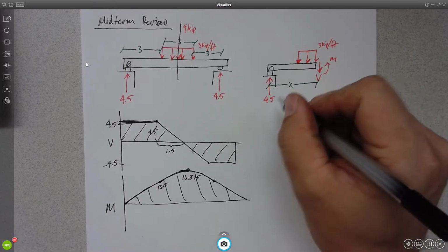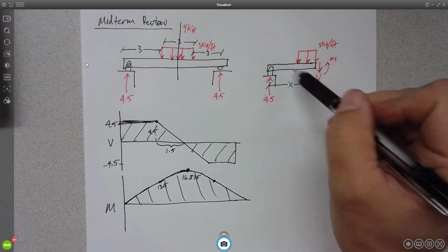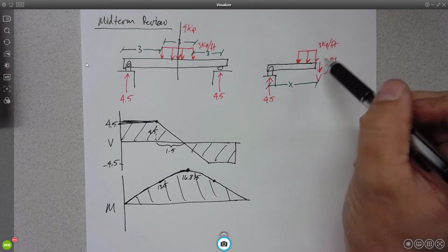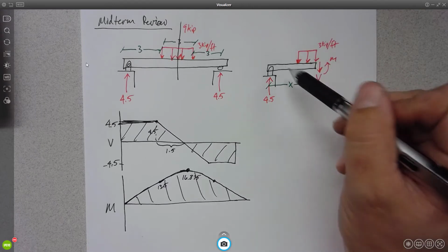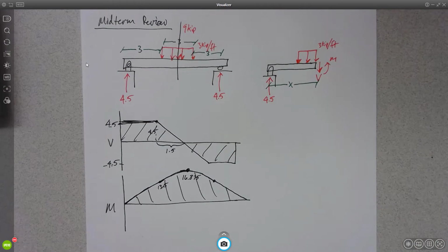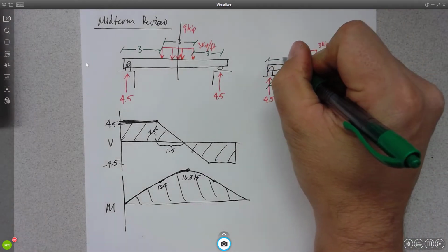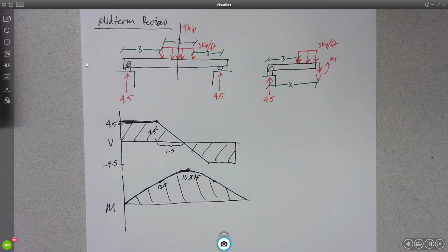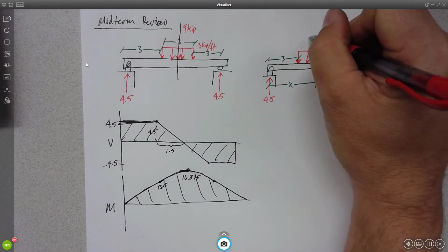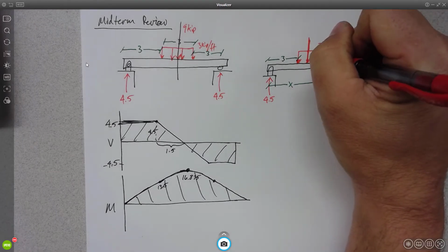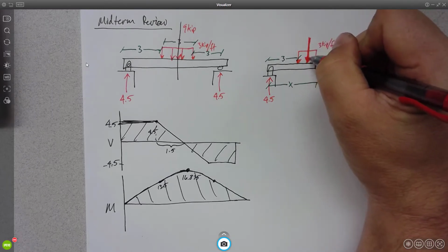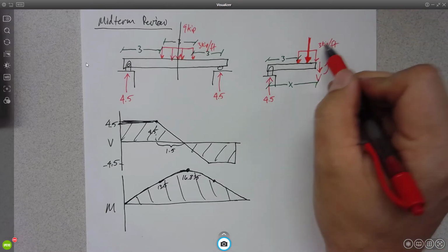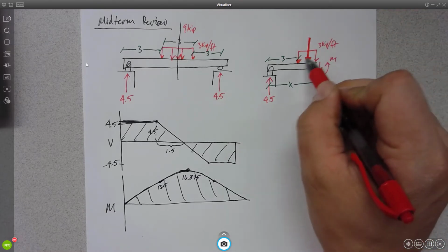It's how we treat this cut distributed load where people often struggle. So how much of this distributed load do we put in here? Remember that this is 3, and we like to simplify this and say that it's one resultant force in the middle for our calculations. The magnitude of this resultant force is the magnitude of the load distribution times its length.